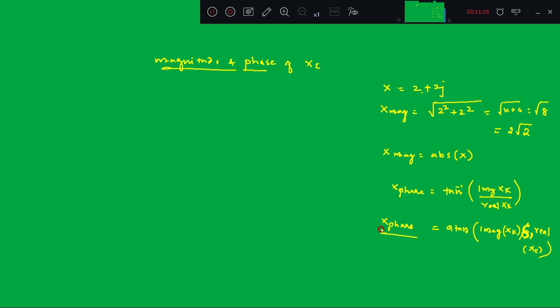Understood? So what is the first part? The first part is to find the DFT sequence, that is xk, right, by multiplying x into the DFT matrix W, where W is exp of minus %i into 2 %pi, then n comma k divided by n, right.